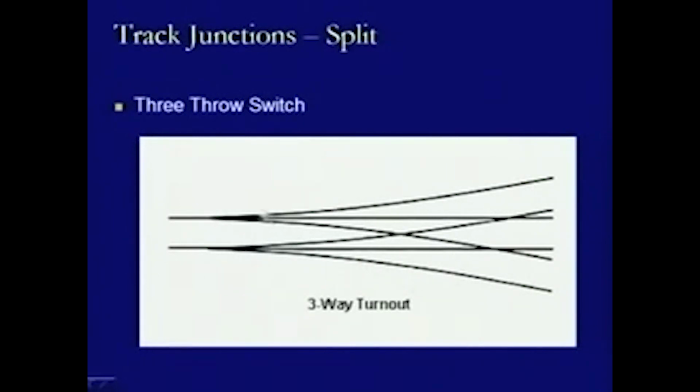So that's why two pairs of tongue rails need to be provided here, and here there is a crossing, as we can see, and this is a V shape. This V shape will be like this, and then this rail which is coming this way will have a wing rail at this location as well as this location. Then we come to this particular location, again there will be a crossing at this location as well as this location. That's why we will have one wing rail condition at this location also.